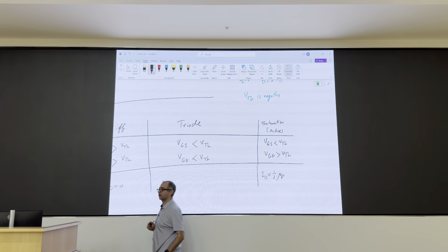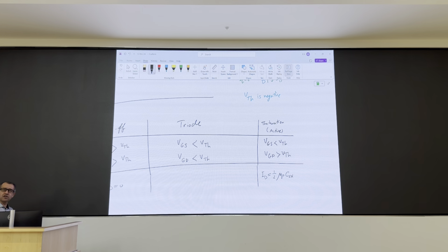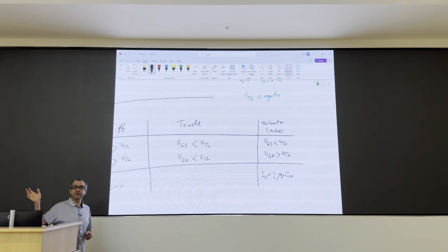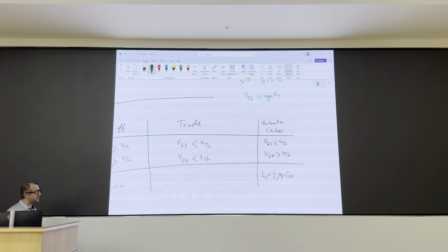They are a little bit different. Of course, depending on the semiconductor you use, they have a different number, but for silicon, it turns out that electrons move faster than holes. So for that reason, NMOSFETs are faster than PMOSFETs. If you have the choice in analog electronics, for example, to choose one of them for your core amplifier, you use an NMOS because it is faster. Same technology, it is faster.